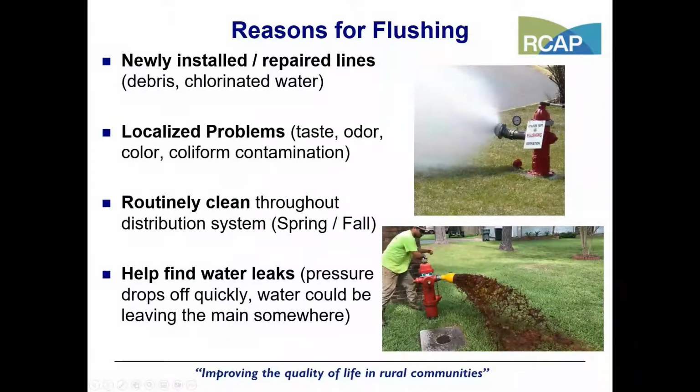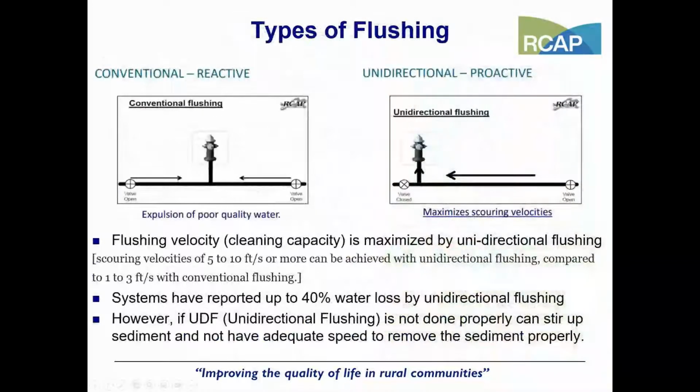As for reasons for flushing, most of you probably already know if you've been doing this for a while. Routinely cleaning is the main thing, or if you have a water break or a localized problem, customers calling in, but also to find water leaks, so don't neglect that. That's a good way to find them, and even leaky hydrants, check those when you're flushing.